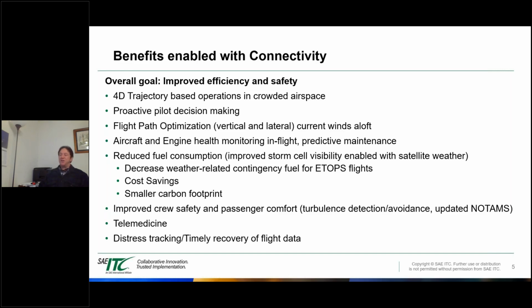You can adjust your flight path accordingly, and then take a less circuitous detour. In addition, with satellite weather, you have a top-down view, which gives you a better feel for how deep these storm cells are, whereas your in-flight radar is only giving you straight-ahead visibility, and so the depth of the storm cells is not very well illustrated.